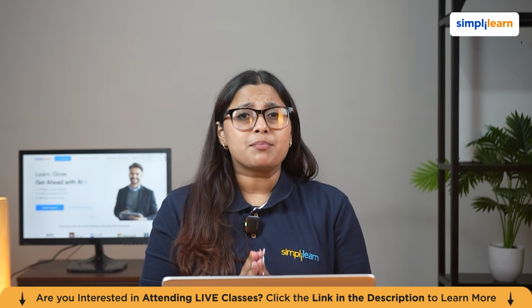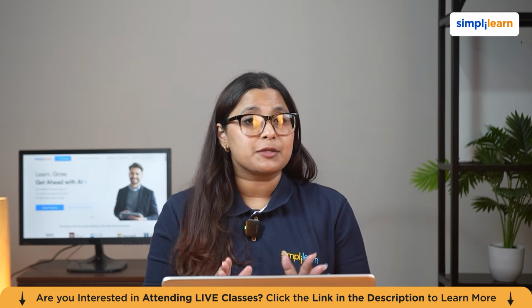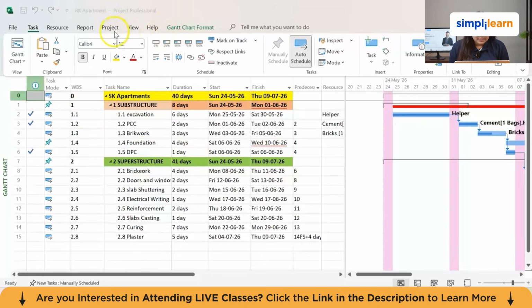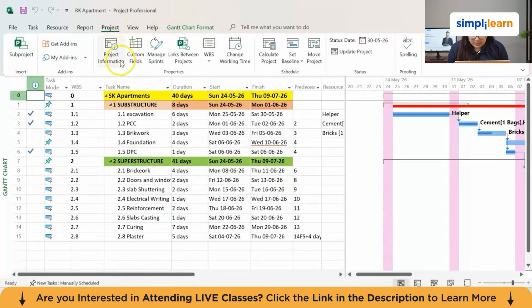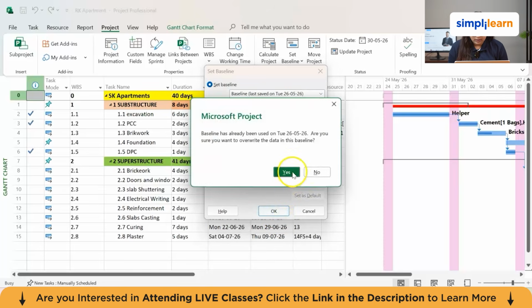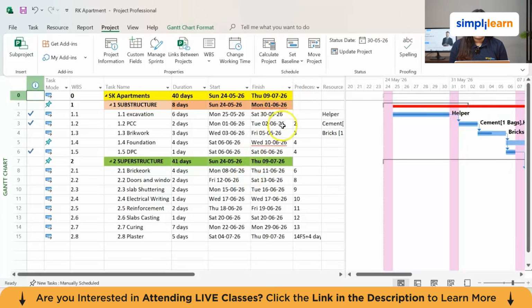The baseline is the most important single action you will take in MS Project, and it takes 5 seconds to set. So let's see. Here we go to the Project tab, click here, and in this we'll set the baseline. In the baseline menu, you come down and choose Set Baseline, and here I can set the baseline as whatever I want. The last one I have done here was on Tuesday 26th. So I'll click on OK, because it is already set here, and we'll move forward with this one.